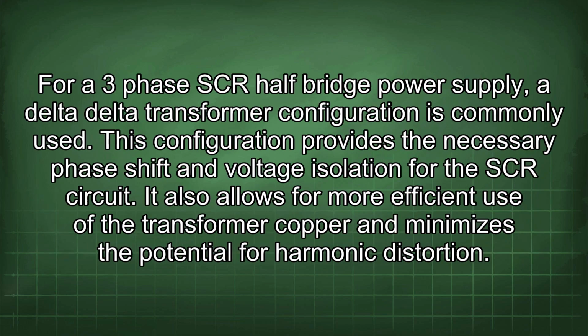For a three-phase SCR half-bridge power supply, a delta-delta transformer configuration is commonly used. This configuration provides the necessary phase shift and voltage isolation for the SCR circuit. It also allows for more efficient use of the transformer copper and minimizes the potential for harmonic distortion.